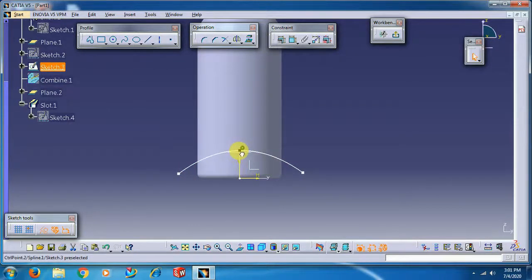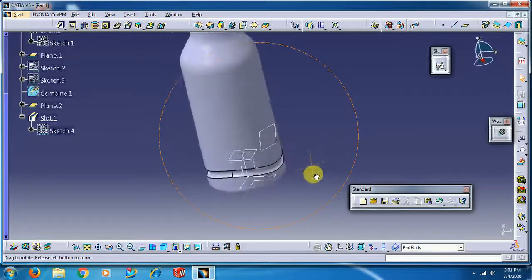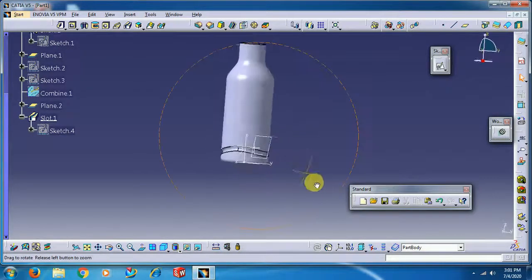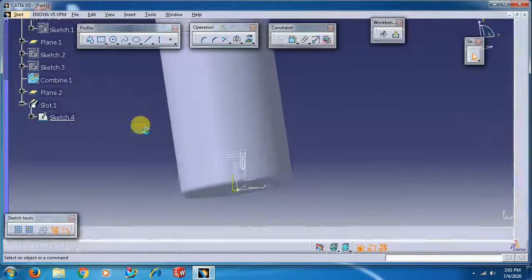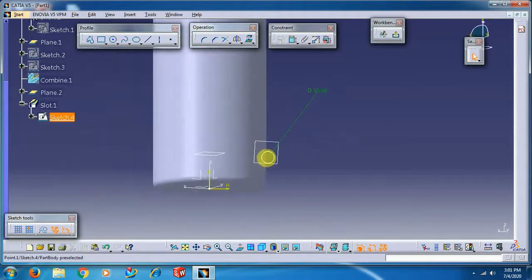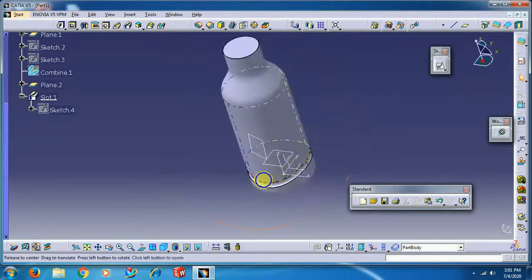See, I want it still more steep. Then I don't want this much depth inside. Then this circle, you just slightly move the circle outside to its end. Less depth, less material removed along that path.